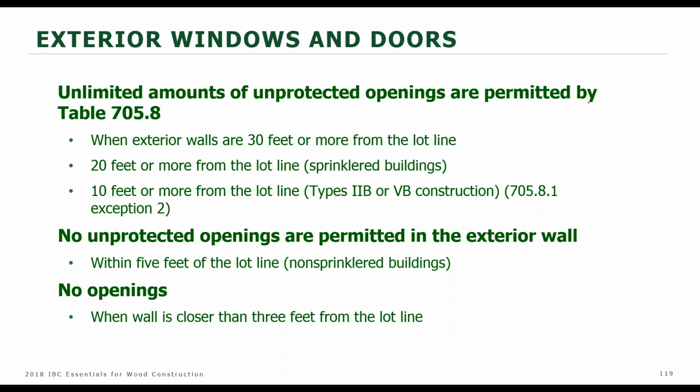As you get closer to the lot line, you get more and more restrictions. Your opening has to actually have a fire protection rating, has to be a tested opening frame and so forth. And then when you get so close to the property line, you can't have any openings at all.